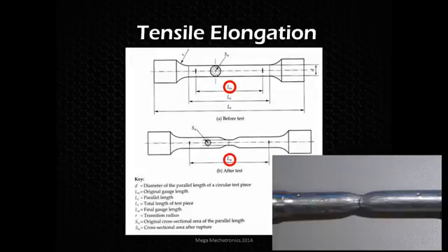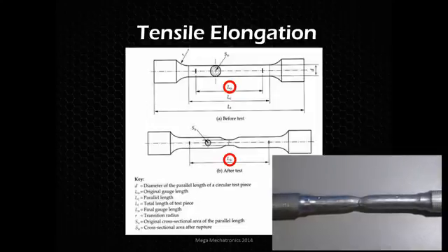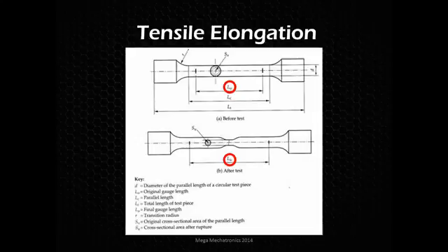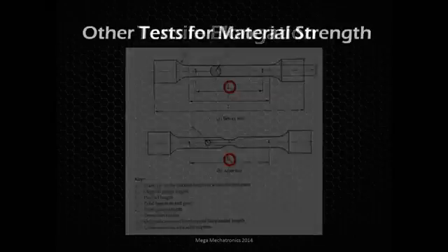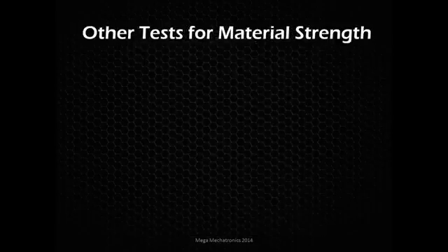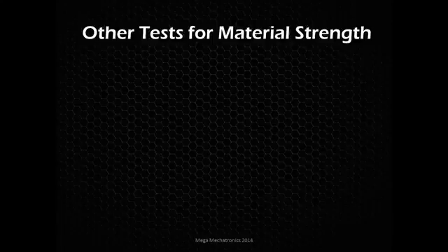So it is actually strain. So if you look at the stress strain curve and at the breaking point, and then you go down to the strain, you're going to see the elongation percentage there. So percent of elongation, that's another proxy to compare materials. And there's still other tests, and I'm not covering every single material test here, just covering the most popular ones.